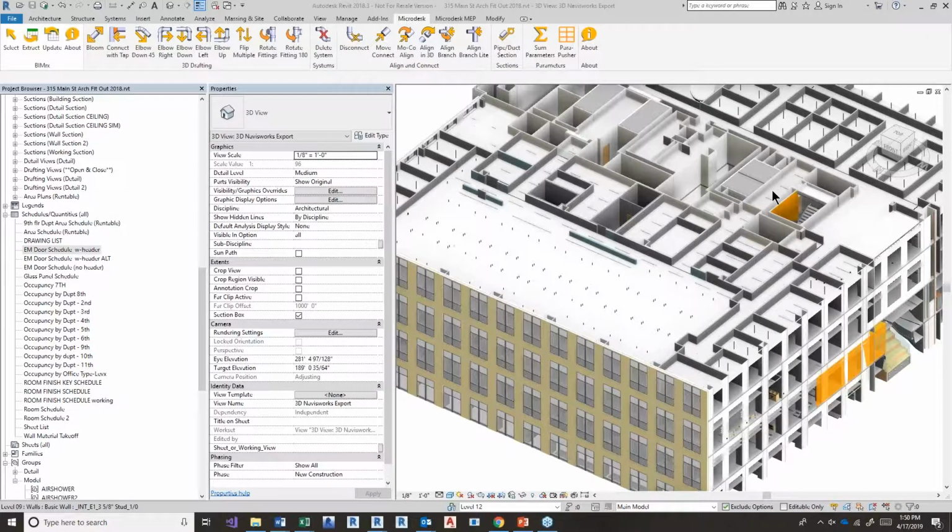With the Revit API, Autodesk is very good at managing code that they deprecate or make obsolete. And in fact, they won't change anything in the API without giving the software developers 1 year advance notification. And what that means is, if our development team has managed all of the warnings correctly in the code, then you should be able to take the 19 version of Revit and basically copy paste the DLL and use it as a 2020 version, assuming you still have Revit 19 installed. So that's a long story to explain that if we did our job at Microdesk, that 19 tool is more or less already 2020 enabled. We simply just have to provide an installer for it.